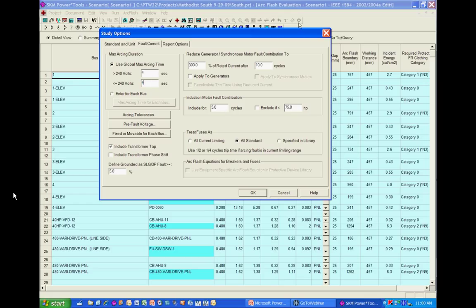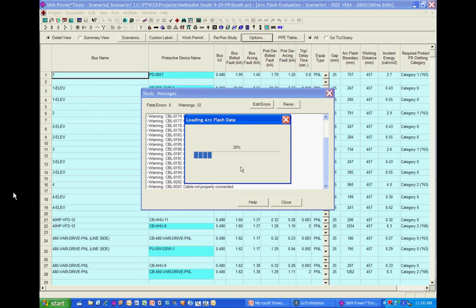And then we calculate the ArcFlash again, okay? And all the different results of ArcFlash for this scenario are going to be, obviously in a lot of places, very different from scenario number one, or the base scenario calculations. So that's where you can manually change all the settings for the second scenario. And you can have 20 scenarios. It's up to how much your computer can handle.